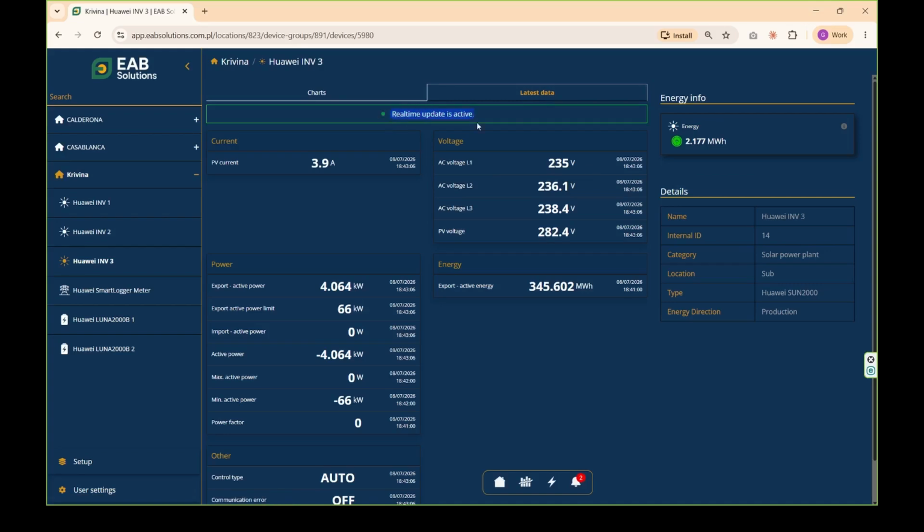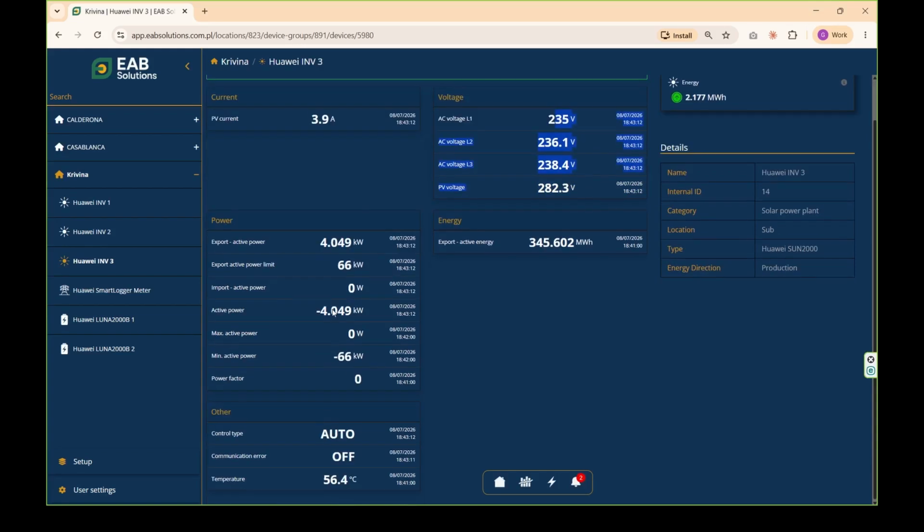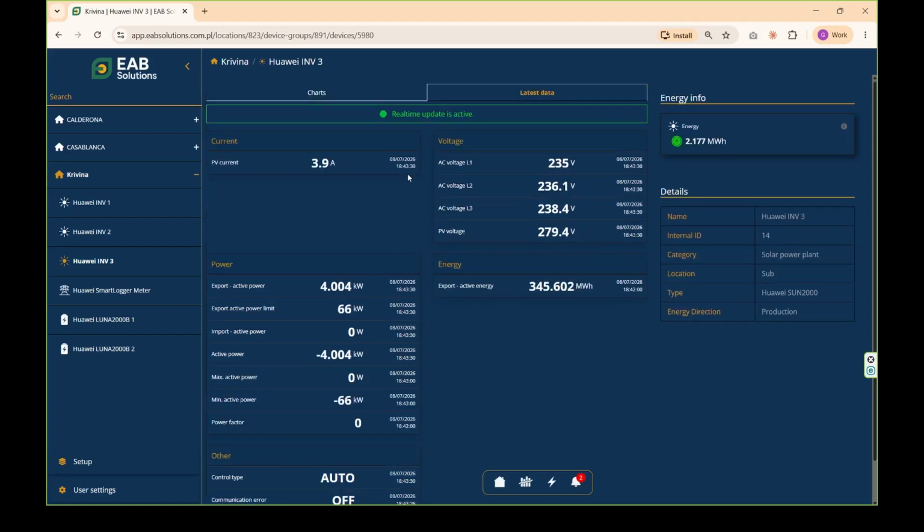Here you see real-time data is shown. It lets us know the inverter is alive, that it's giving voltage, current and power values that are correct, that there's no alarm and that its temperature is right. We've tried to bring the client here the minimum data that carries relevant information. There's a lot more data that we as installers and system managers have, but that isn't relevant to the client, and so we don't bring it here, to avoid making this platform too complex and cumbersome.